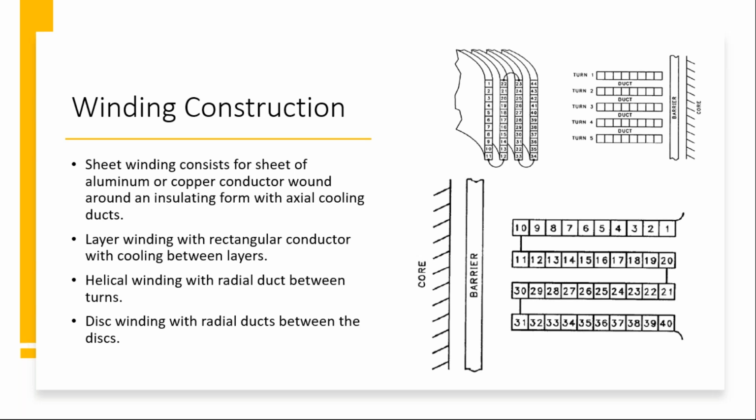The second would be a layer winding, which is commonly used in industry as barrel winding. Here the conductor is wound from bottom to top or top to bottom, putting in multiple layers. Here again, the conductor is small, and it has limited inbuilt strength against the forces. So now these two constructions are very common for small-rating, distribution-size transformers.